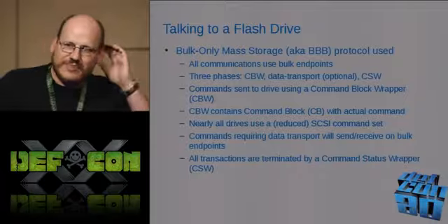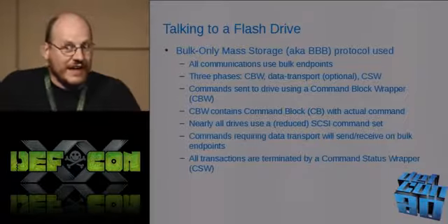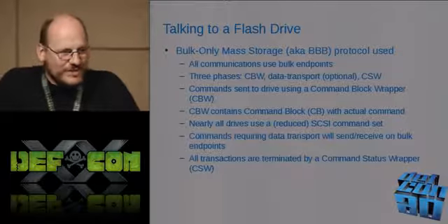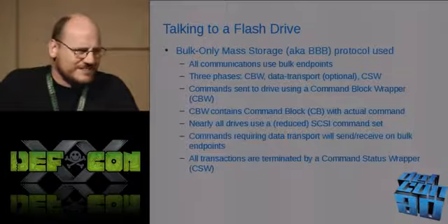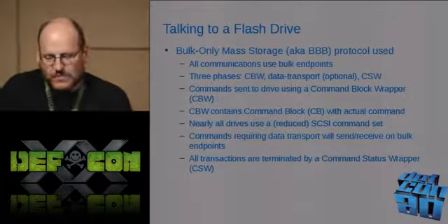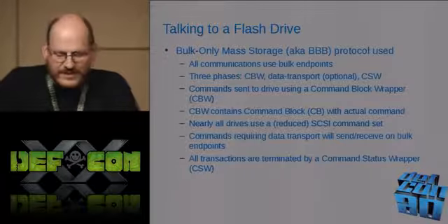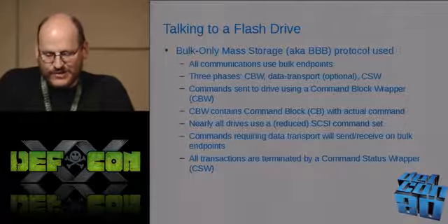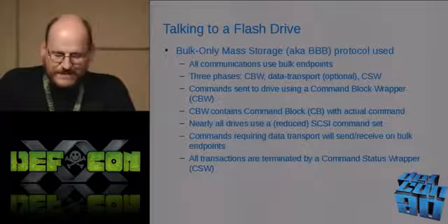There's a command block wrapper phase, where you send a command block in a wrapper, data transport, depending on the command, and then a command status wrapper where you say, hey, did this succeed or not? Most of these drives use a reduced SCSI instruction set, and if you have to send or receive data, you use a bulk endpoint for that.